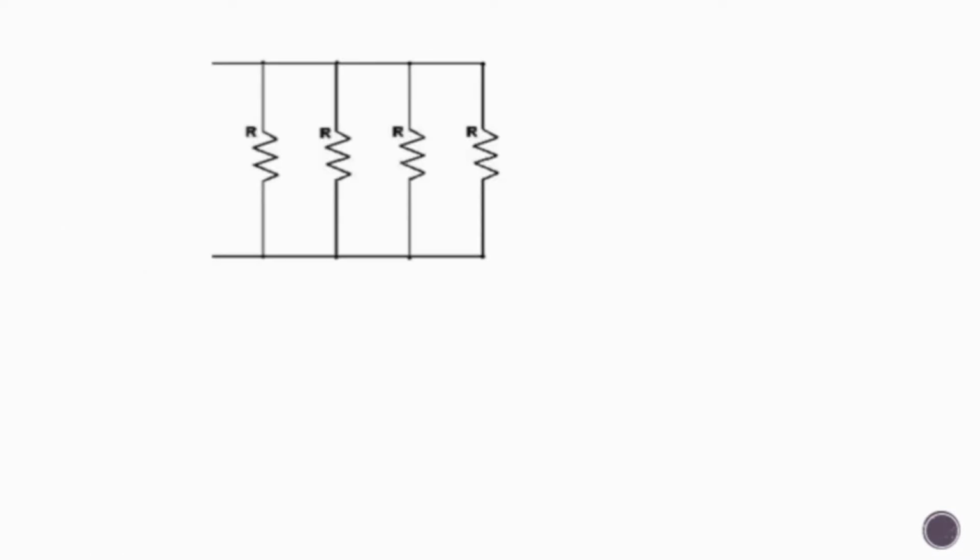There are multiple parallel paths and each have a conductor. The induced EMF of one conductor is from here to here. The EMF induced in each parallel path is the same, and it is calculated by the total number of conductors in armature divided by the number of parallel paths in which conductors are distributed. And these are the conductors across which EMF is induced.